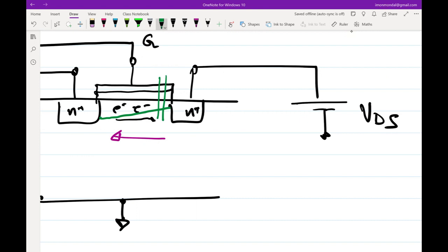The charge underneath the channel in that sliver for this small MOSFET will be proportional to the voltage difference between the gate and the channel, right? Now the voltage at the gate is VG, and the voltage at this particular sliver of the channel, let's call it Vx. Since the voltage across the oxide is Vg minus V of x,